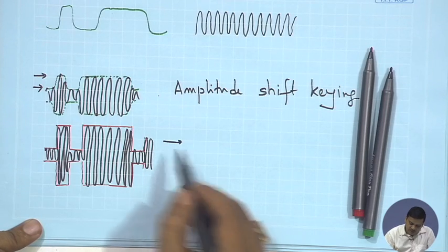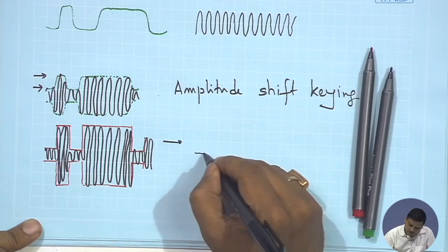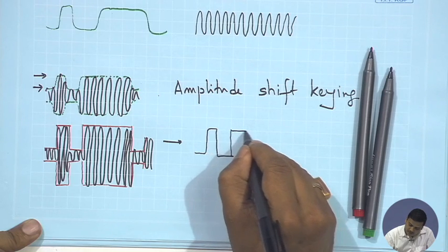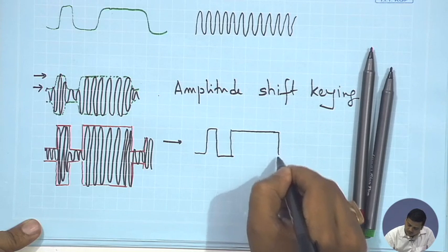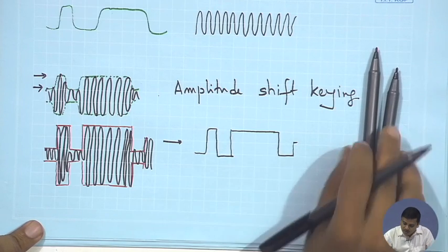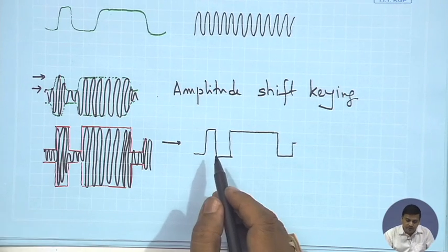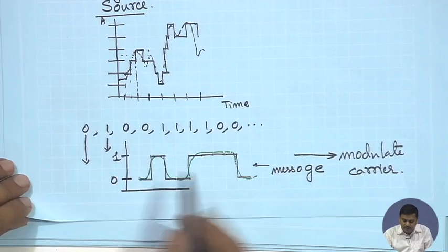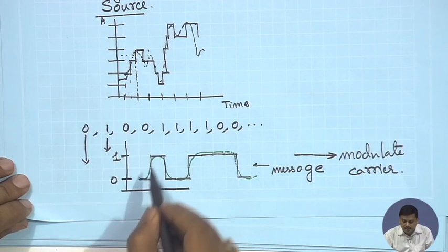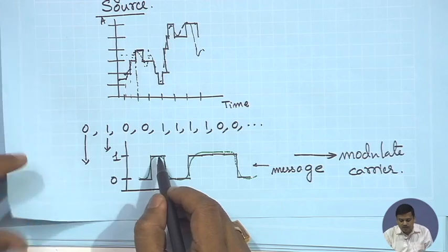So when your amplitude modulation receiver acts on this particular signal, it's going to generate the envelope of the carrier, or the amplitude. It's going to generate this waveform. Now, once you have generated this, you can reuse your earlier mapping: if the signal level is here, I would consider a 0 has come. If the signal level was there, I would consider 1 has come.